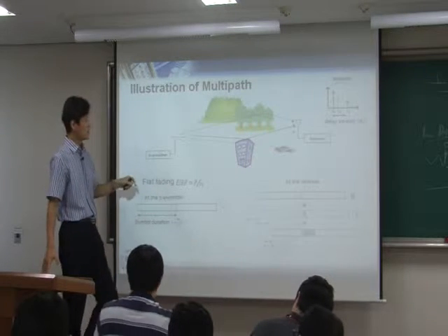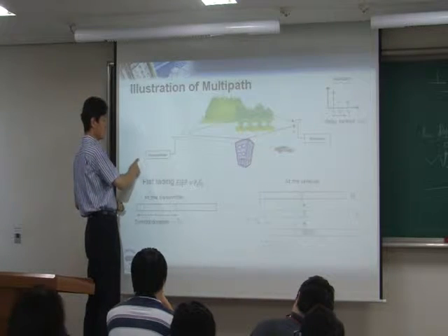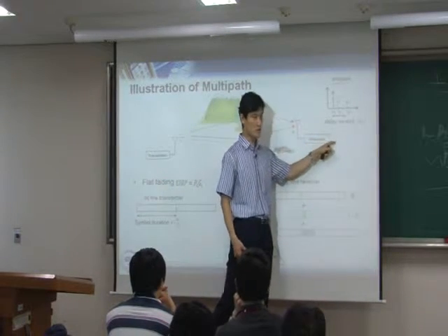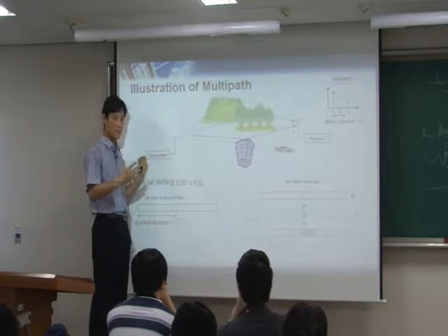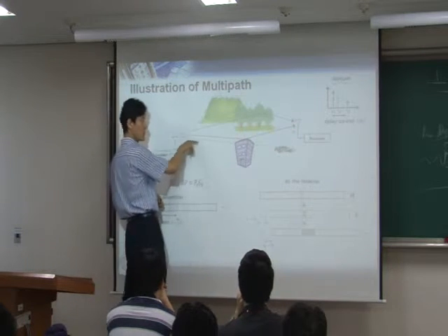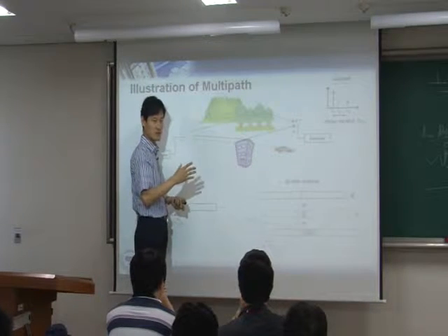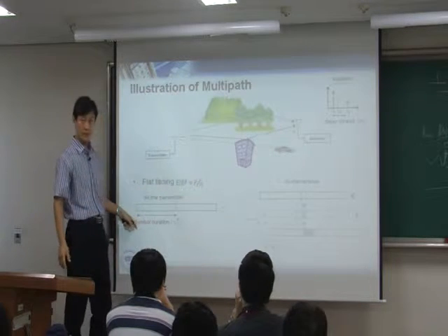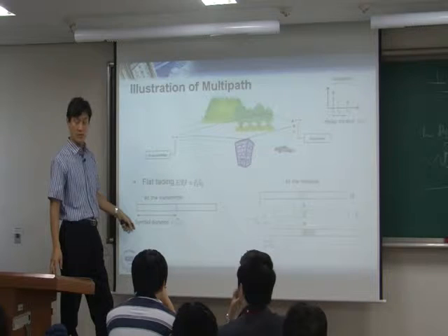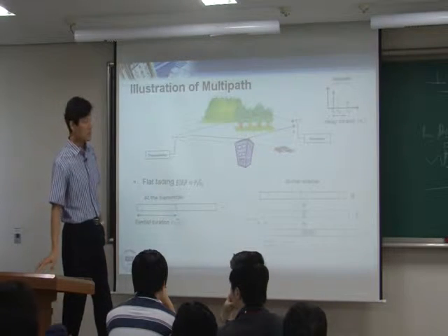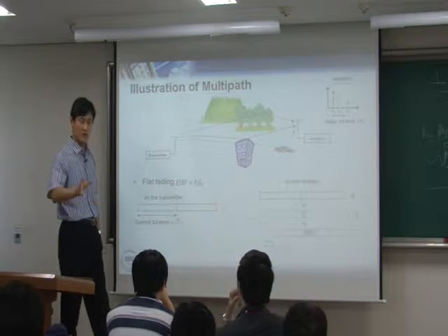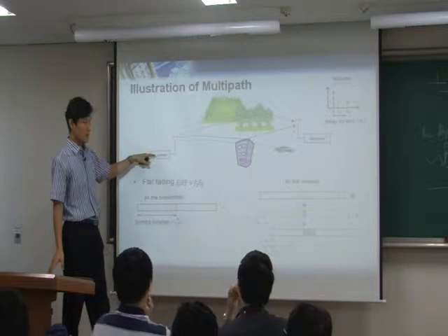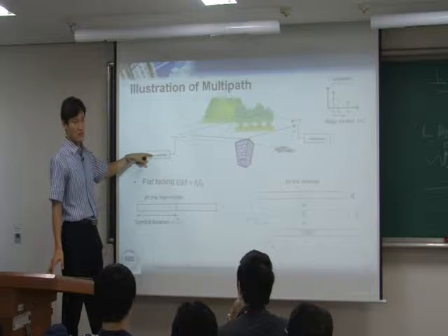It's conceptually correct. But when we talk about the bits, that's like something here and something here, right? After you do all this processing, you eventually recover the bits. Originally, you want to transmit bits. But when you go through the channel, you are not transmitting bits; you are converting the bits into symbols. Symbols are like voltage levels. It could be voltage levels, it could be phase, or it could be anything else, right? But a symbol is different from a bit. Eventually, you change the bits to symbols. The easy way to do it is modulation, right?